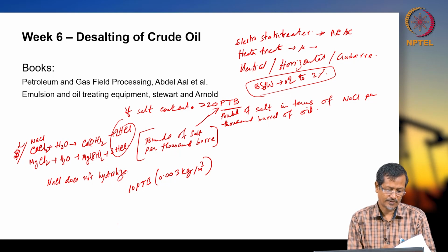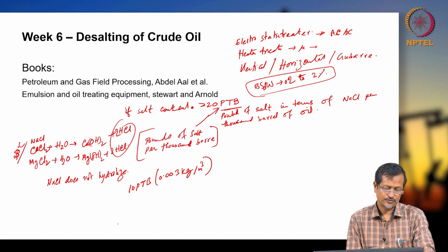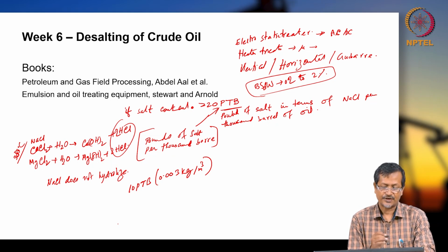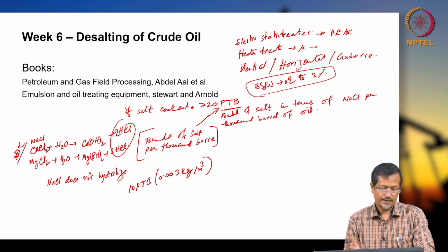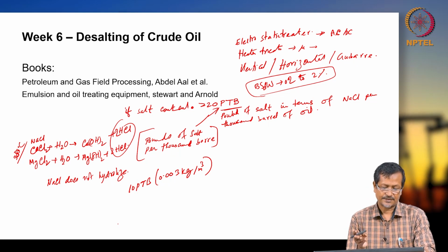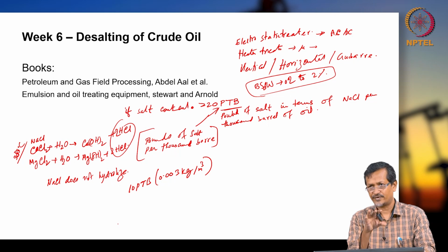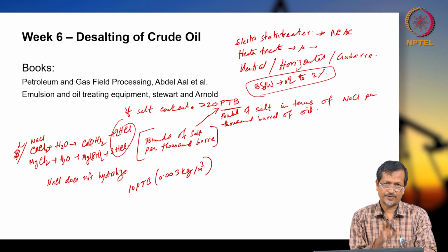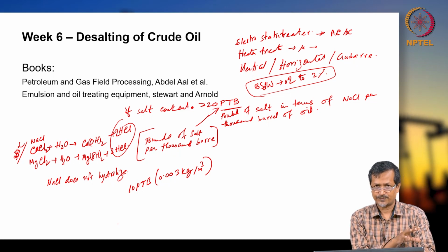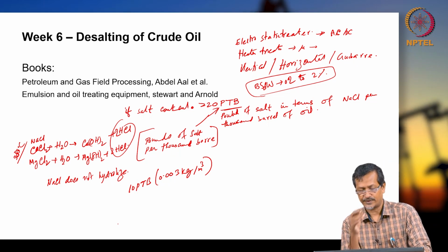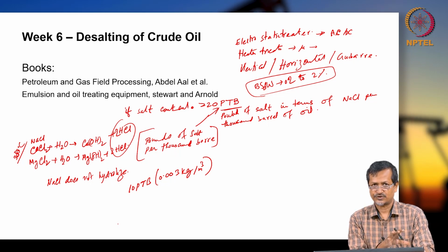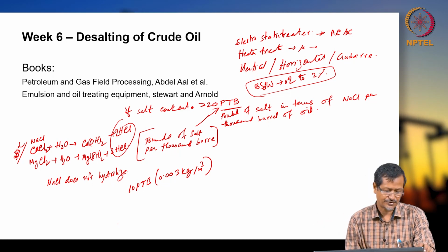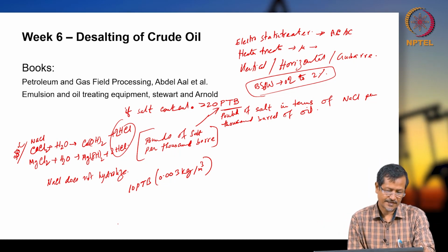Salt will be doing some more action also. Salt crystals will be deactivating the catalyst bed, and it will plug downstream processing equipment in the refineries. Okay. So, in refineries there will be catalyst to convert crude oil to different components. So, that will be deactivated. So, that will be another problem. So, first you have to remove salt, means surface production operation people will be doing some part, maybe some part will be done by your refinery people, or maybe surface production operation salt removal part will be enough for your refinery application. Desalting: removal of water as much as possible.